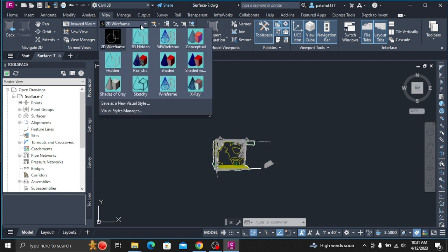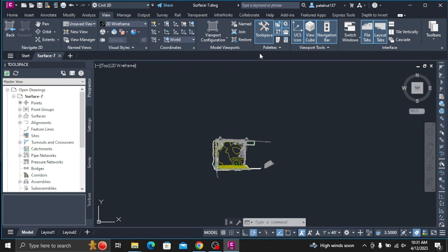Repeat steps 6 and 7 to insert the light pole 01.dwg block. When prompted to specify an insertion point in the drawing window, click the symbol near the middle of the median. Press Enter to accept the default scale factor and rotation angle. Move multi-view blocks to the surface.